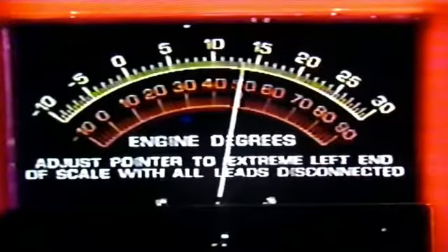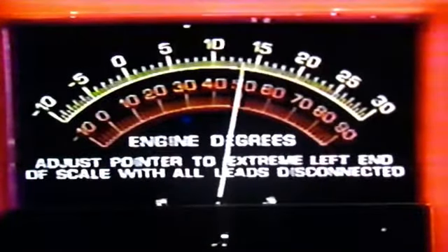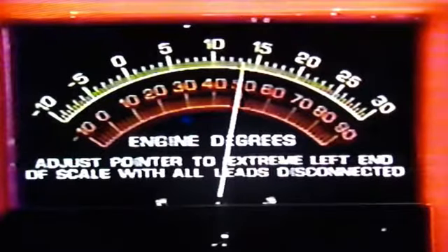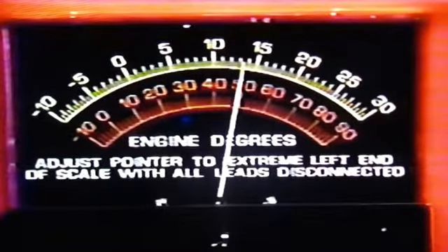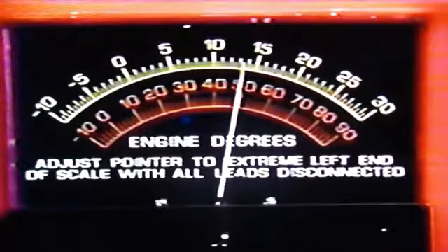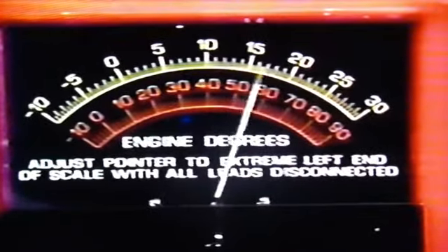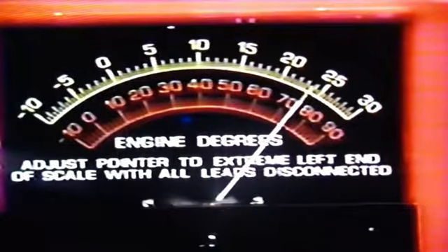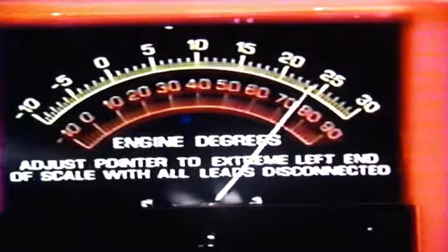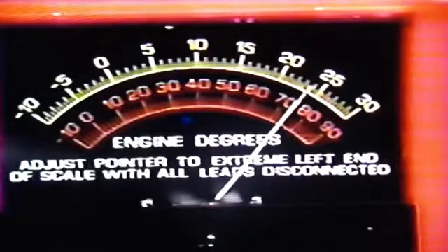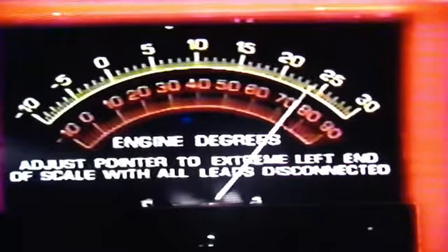With the engine running, we look at the advance meter and see that this engine is at about 13.5 degrees. The specs for the engine say it should be at 15 degrees, so we'll need to loosen up the distributor and reset it for 15 degrees. Once the computer is out of the system, we speed up the engine to 2,500 RPMs to see if the timing changes. The meter shows timing did change, which means the HEI has change capability and the timing module is functioning properly.